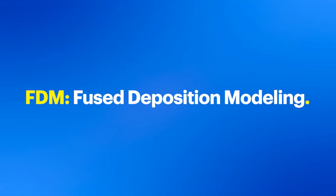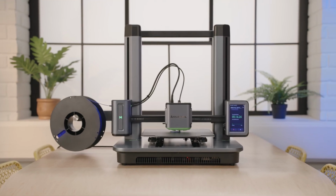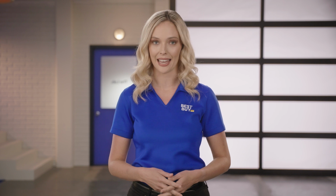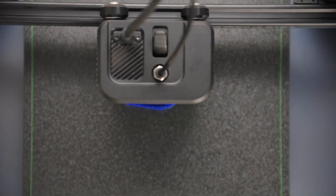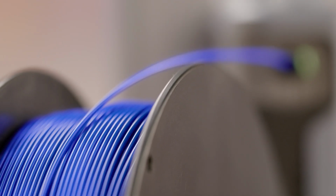There are two main printing technologies in use today: fused deposition modeling, FDM, and stereolithography, or SLA printing. FDM printing adds material one layer at a time to an object, and SLA printing uses light to solidify single layers of material at a time. Both are considered additive manufacturing, meaning material is added a layer at a time to make the whole object. The main difference is in the way the material is added. Today, we're going to focus on the more popular of the two technologies, which is FDM printing.